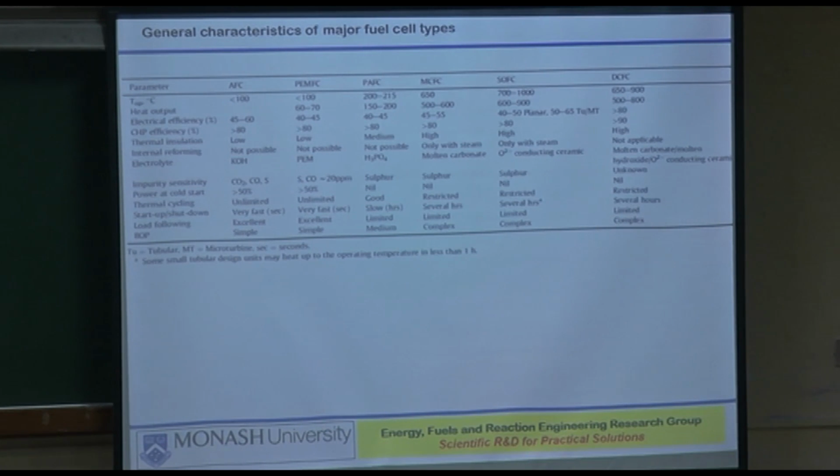So the point I'm trying to make is that as soon as you go towards the higher temperature fuel cells, which is MCFC onwards, they open up the possibilities for accepting new fuels other than just hydrogen, and also reforming in situ, and also the ability to go higher up in the size.